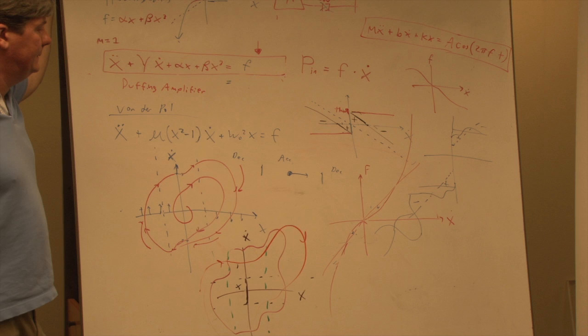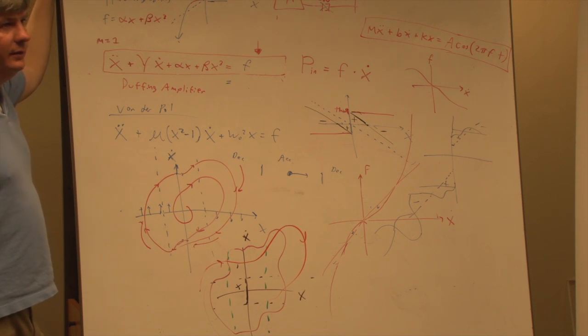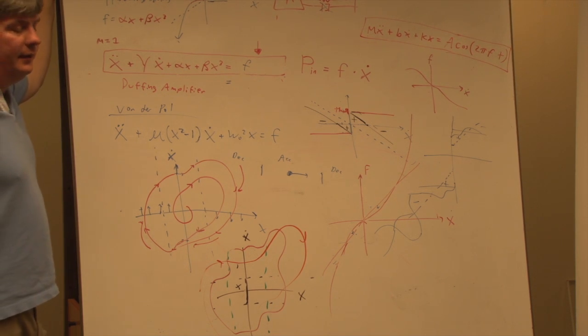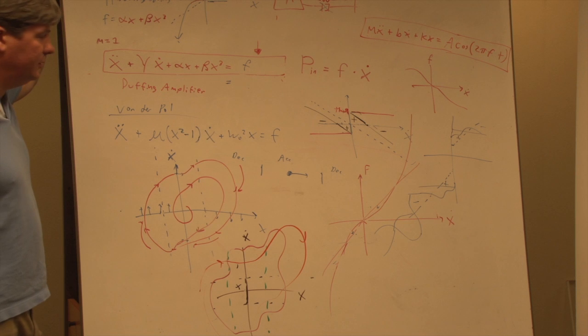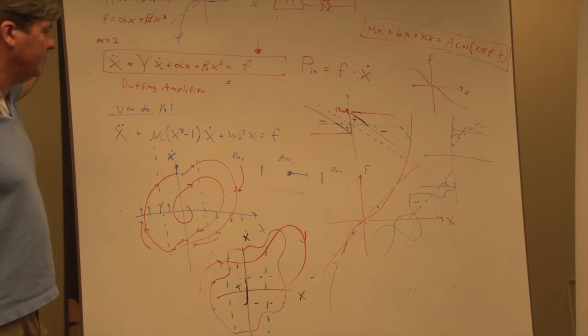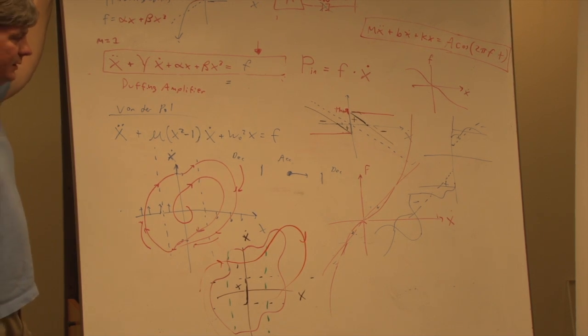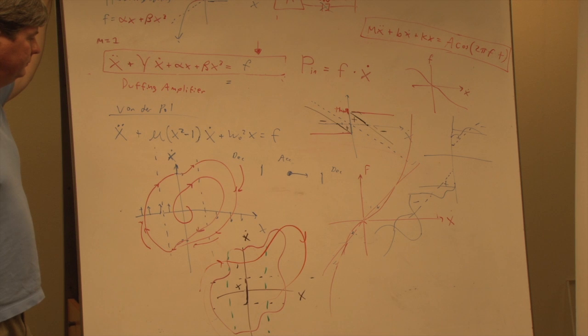And we want to use physical springs to save the real energy. Because if you emulate a spring with a motor, you're not going to get the energy back very well, even if you have a regenerative brake or something. And then the other effect is that springs and dampers happen instantaneously. You don't have to worry about control loop rates and stuff like that. You can have an infinitely stiff spring that you actually build and it works really well, whereas if you try to do one control-wise, it works horribly. Or a very stiff spring. So an easy to remember rule of thumb is no virtual springs, but if you need them, virtual dampers. That way you maintain the energy.